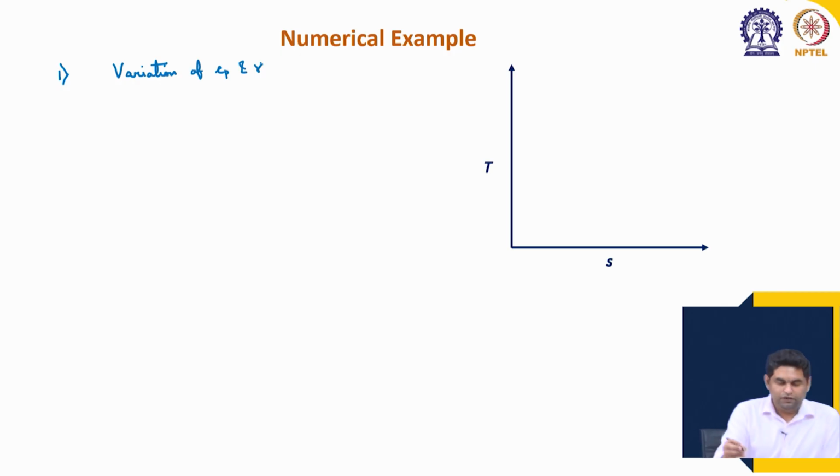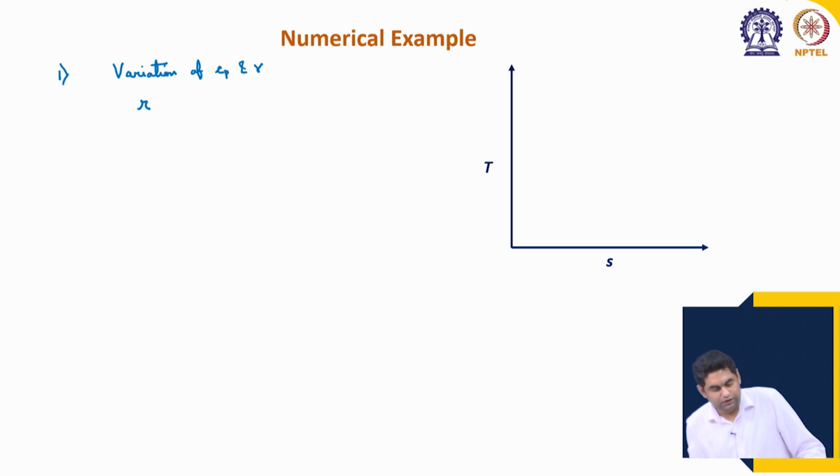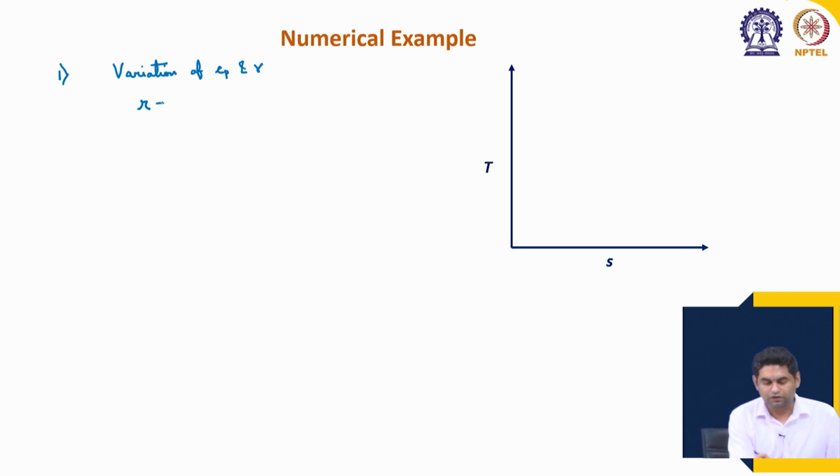We have a gas turbine with a compressor pressure ratio of 10 without any losses. The temperatures are also given. Let us use stagnation values to make it more accurate. T01 is 300 Kelvin, T03, which is the Tmax value, the turbine inlet temperature, is 1500 Kelvin.